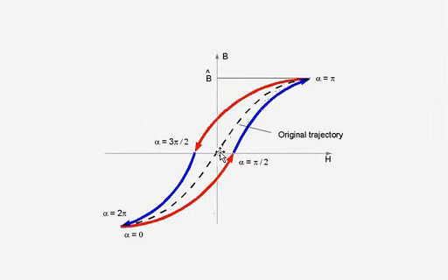So if I solve a quarter cycle in that direction, the Steinmetz losses are going to be exactly the same as if I solve a quarter cycle back in that direction, and also exactly the same as if I solve out in the negative direction and back into there. So I only need to do a quarter of what you might think you need to do in a full cycle.